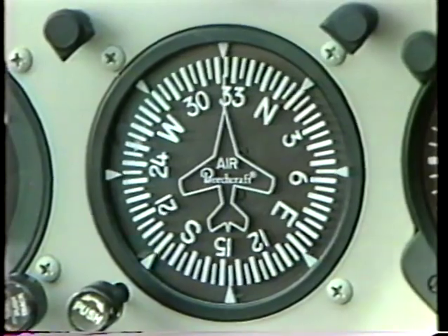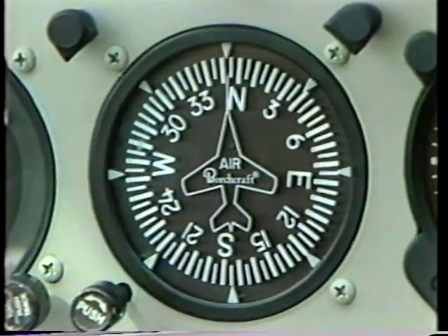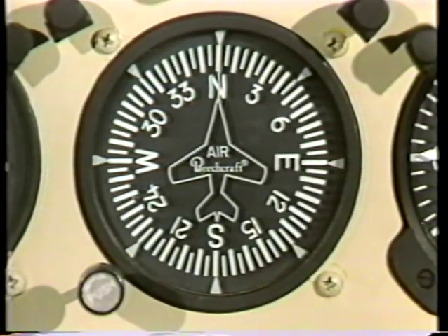Except for situations involving excessive angles of bank or improper setting, this instrument is extremely reliable. Precession does act on this instrument, but unlike the attitude indicator, the heading indicator does not have the internal capability to correct for precession errors. Consequently, the azimuth card will drift from its correct setting during flight. This gyro drift requires the pilot to reset the heading indicator to a reliable source of heading information, such as the magnetic compass.